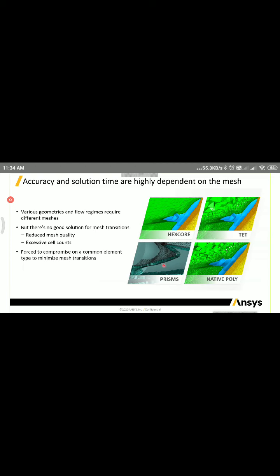Right? So that's how all the strategies of the meshing or the geometry modeling affect your simulation. Say, for instance, you are doing an external flow and you are interested to see how much the flow is going, what is the pressure drop across the engine. You cannot block it. You should allow the flow to go through the engine. So that strategy we have to apply while modeling the geometry or while considering the volumes.